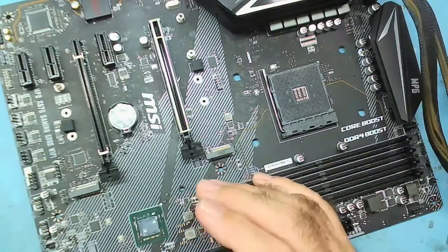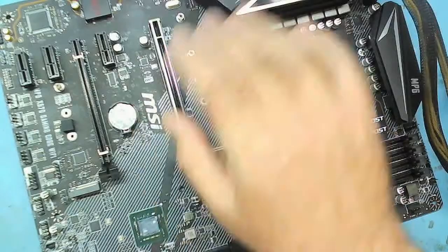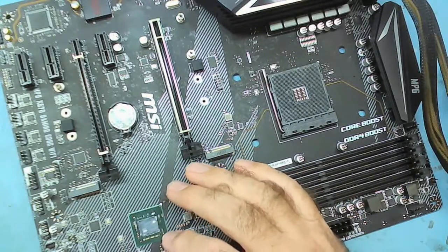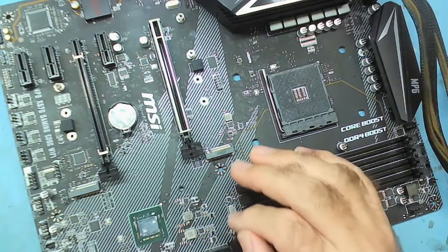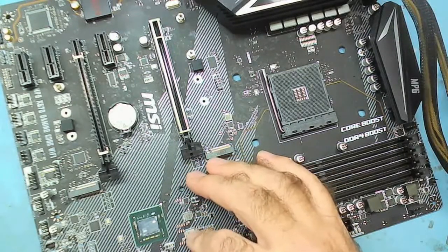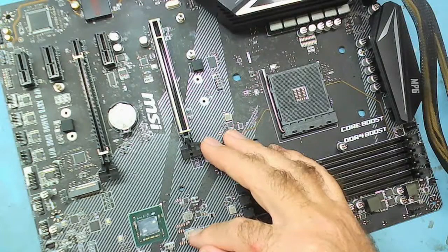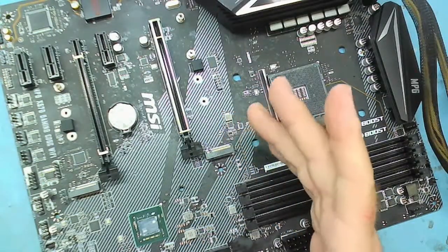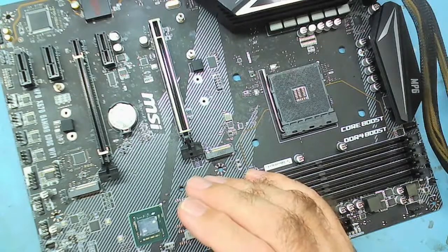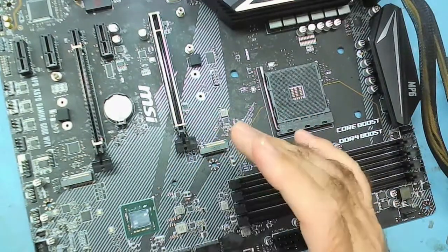So the only realistic explanation for that is the 5 volt standby comes in. It goes to some regulator somewhere and puts 3.3 volts over here. It goes to another regulator and puts 1.8 on here. And then from that 1.8, it goes to another regulator, and that derives the 1.8 into the 1.1. So if your 1.8 is low, about a third, 0.7, your 1.1 is going to be low, about a third, 0.3. That is the logic that tells me I've probably got a regulator on here that should be generating 1.8 that ain't, it's giving 0.7, and then that 0.7 is going to another regulator which should give 1.1, it ain't, it's giving 0.3. And I think that's most likely what we got.